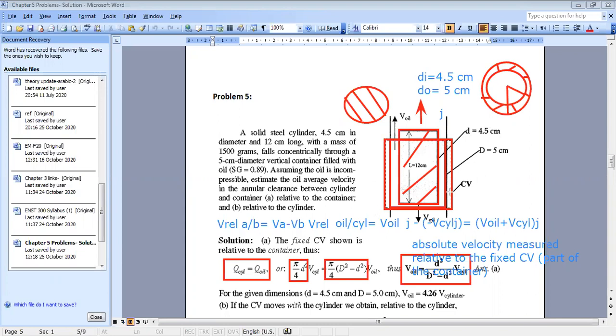Doctor, you were saying I can apply continuity whenever I don't have what? Look, the continuity equation is always applied, but in the continuity equation you have a transient term for mass. So here you cannot say that mass is conserved at any time. Why? Because I will show you, for example, as your cylinder enters the control volume, if your cylinder is now just here at this location, is the mass the same inside your control volume?